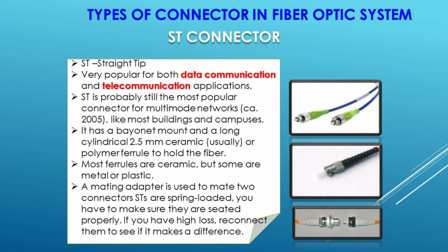A mating adapter is used to mate two connectors. STs are spring-loaded. You have to make sure they're seated properly. If you have high loss, reconnect them to see if it makes a difference.